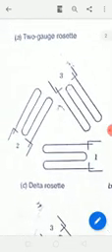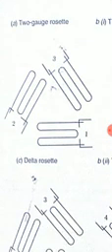So the next one is the delta rosette, and you already know that. The symbol is delta. The gauges are arranged on this delta rosette. We can say one is arranged in the horizontal direction, and the other two are arranged as the remaining sides. We also have to observe that it looks like a triangle, right? I can say that one is 0 degrees, another one is 120 degrees, the interior angle is 60 degrees, and another one is 60 degrees, right? In this way, if you orient them, we can call it a delta rosette.